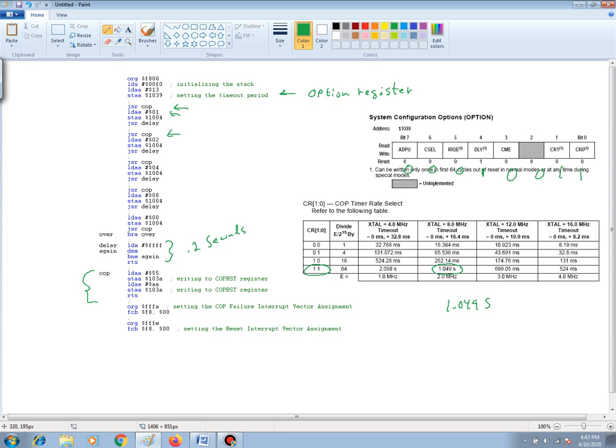So it goes back to the next line of instruction, which is to load accumulator A with a 0, 2 and store it at port B. Then it goes to a delay. So now LED 1 is on. And if we were to put some LEDs over here, something like this, there's 4 of them. So this is LED 0, this is LED 1, LED 2, and LED 3. So now LED 1 is on, and it stays on for about 0.2 seconds.